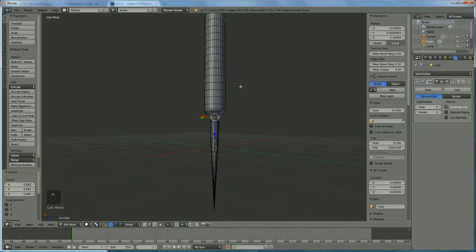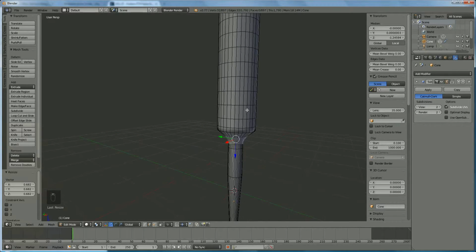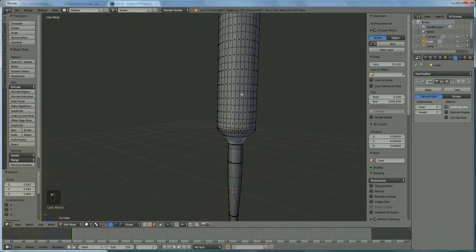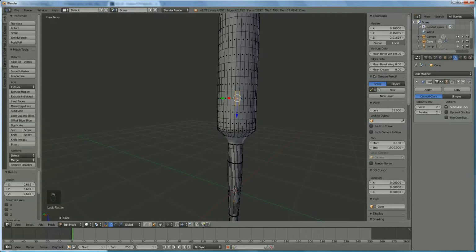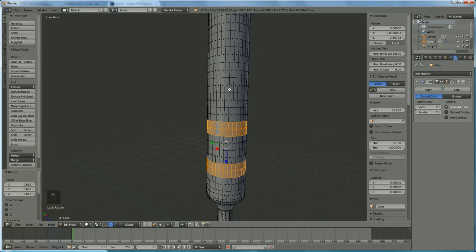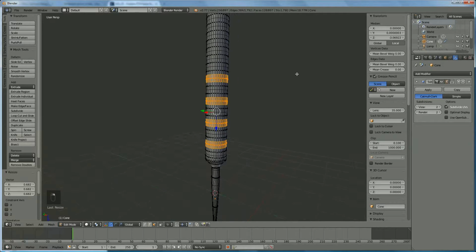Okay, now we're going to add a few extras. So to do that, we're going to select, face selection, that, hold down Alt Shift and click on that vertex. Let's say this one, leave 2 in between, move it up a little bit, 2 in between, 2 in between, let's say 3, 4, 2 in between, and that one, approximate, that one too.